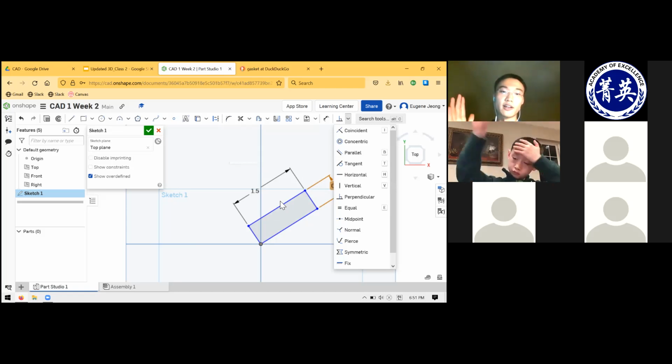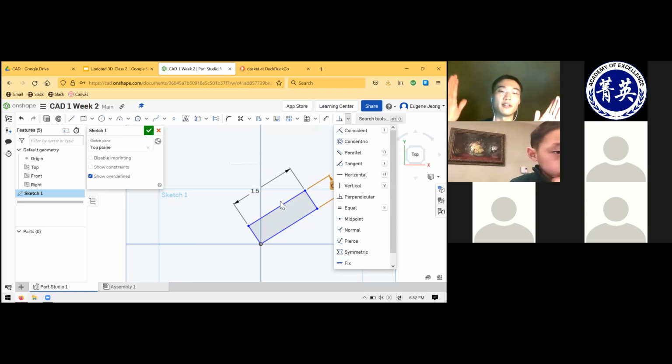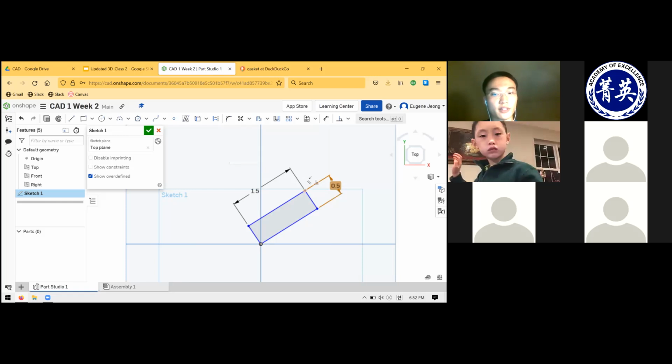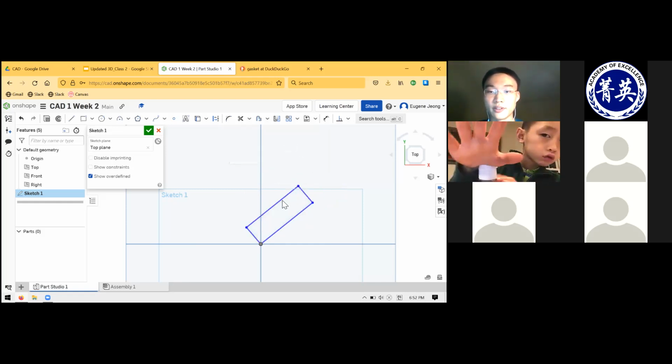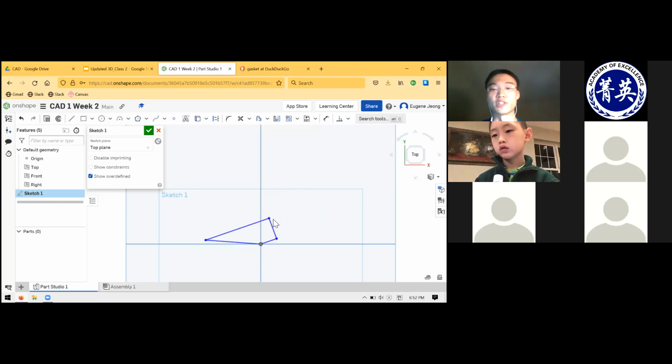to each other, and then the opposite ones have to be equal. And that's just as valid as what I did, which is saying that opposite lines have to be parallel and adjacent ones have to be perpendicular. But make sure, go through and see which of the relations that you're missing. If the shape is deforming, that really suggests that maybe you forgot one of the relations. And for example, if I delete one, now I'm able to deform it into weird shapes again, you see?